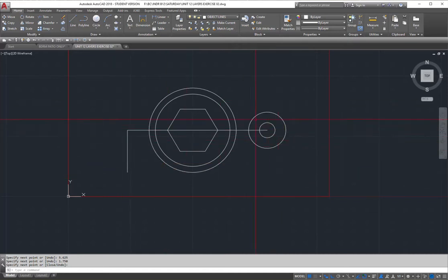Now I could recreate these two circles right here as well, or I can simply copy these two objects from this center to that center. And now I can select this and delete them. Okay, so I have the rough parts of this shape. Now I just have to find some additional points that I need. There's going to be a line that goes tangent from here to here, a tangent line, and there's going to be another one that goes tangent right here.